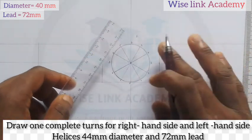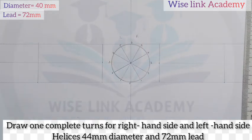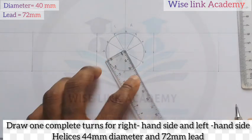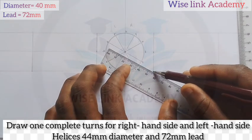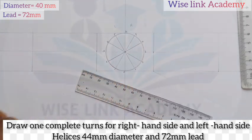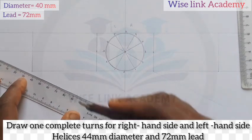Now I want to divide this line into 12 equal parts. I can take either this upper part or this lower part, any one of my choice. So let me just take the lower part. Let's take it this way. Just draw an inclined line of your choice, draw it down this way. Similarly, come to this point, draw an inclined line of your choice. Let's take it down this way.